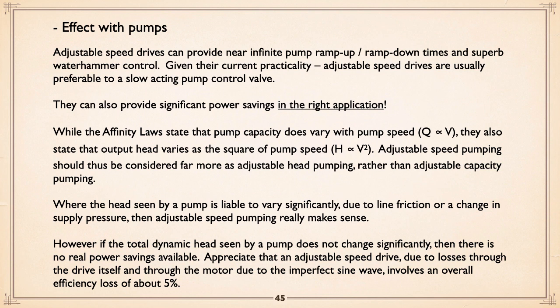Given their practicality, even slow-acting pump control valves in a lot of applications. I'm not a big fan of pump control valves, to be frankly honest. If you really want to control, a better approach is the solid-state starter with soft stop, if you can live with that 30-second limitation. If you can't, then you start looking at drives.